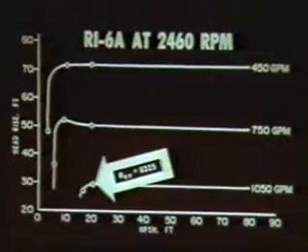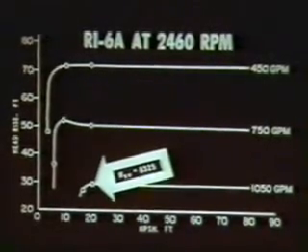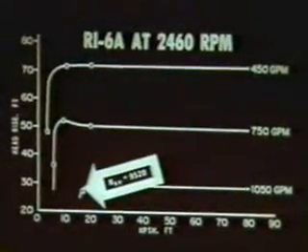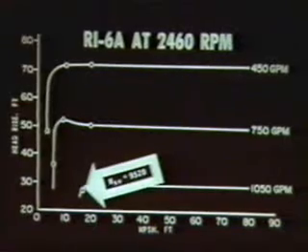Localized cavitation exists on both surfaces of the vane leading edge. Also, note the tip vortices in the rear channel. Note the tip vortex on the pressure surface and the increased cavitation in the rear channel. Cavitation now extends completely across the tip of the rear channel.